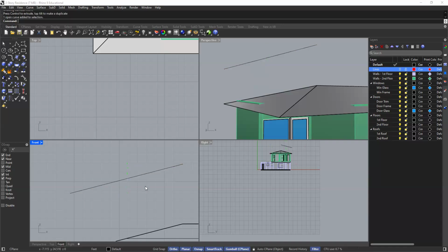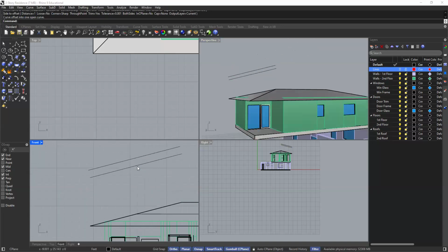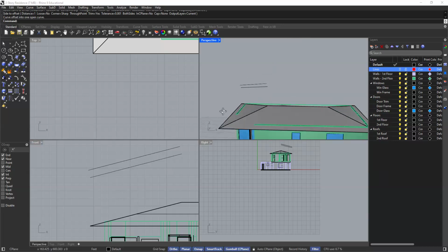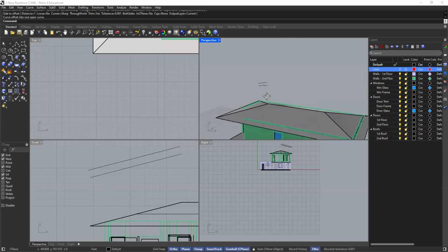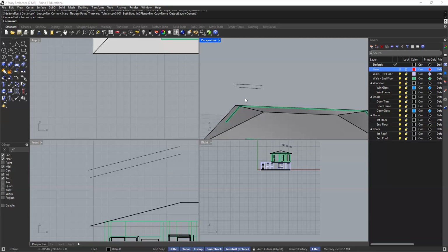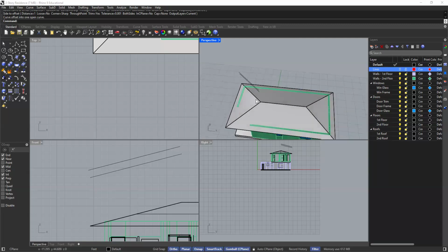And then we'll offset this 12 inches. Now it's important that you do this part in the front view, okay? Because technically here you could see that it's working well, but in a perspective mode, you realize that we're actually at an angle here. And that becomes a little bit harder to work with these dimensions where it's kind of shooting at an angle like that.